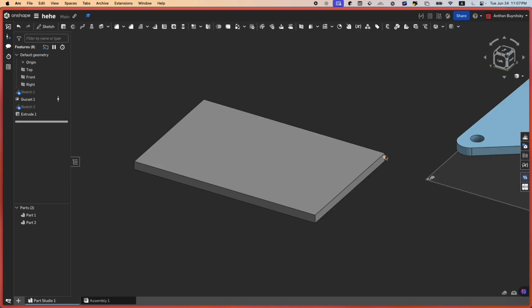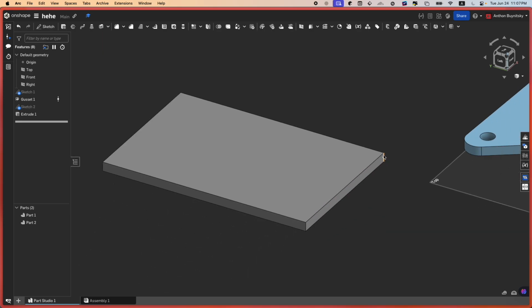Filleting is also really important when it comes to inside corners because the CNC cannot give you a sharp inside corner. There's always going to be a radius there. Yep. And that depends on the diameter of the drill bit, right? Or the radius? Mm-hmm. And mill.